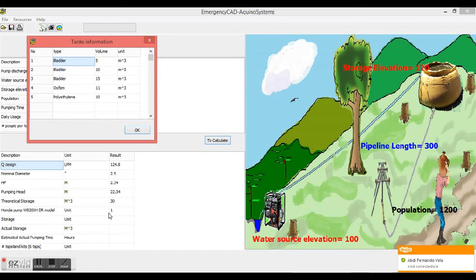We can have other cases where we may need more than one water pump due to a higher pumping height, in which case we can install several pumps in series, or other cases where the flow is such that we have to install several pumps in parallel.